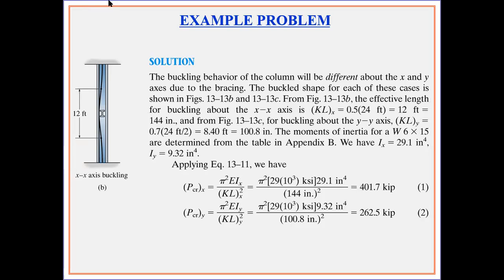Exactly, because both the ends are fixed, your k value is going to be 0.5.